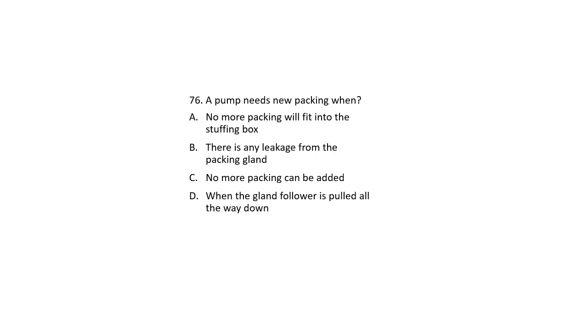A pump needs new packing when no more packing will fit into the stuffing box, there is any leakage from the packing gland, or no more packing can be added when the gland follower is pulled all the way down. And the answer to that is when the gland follower is pulled all the way down.